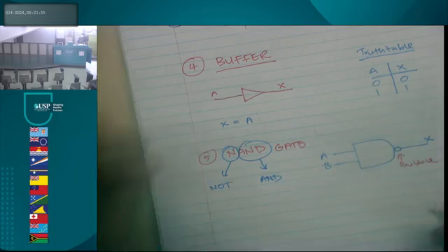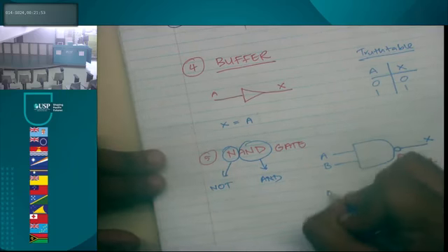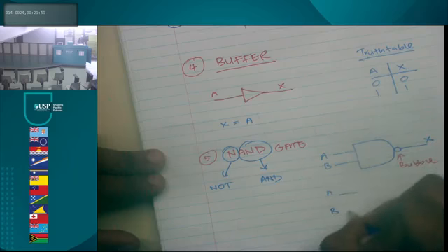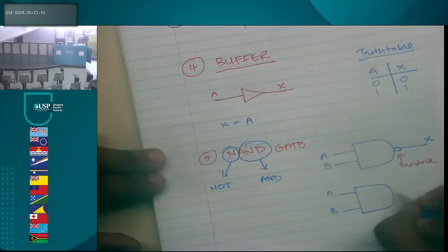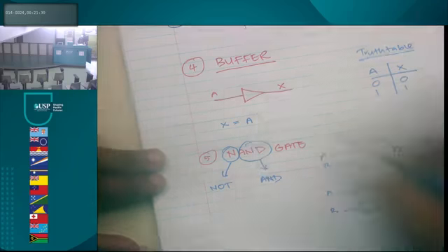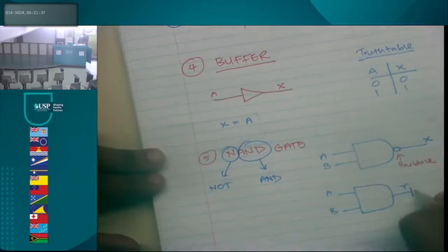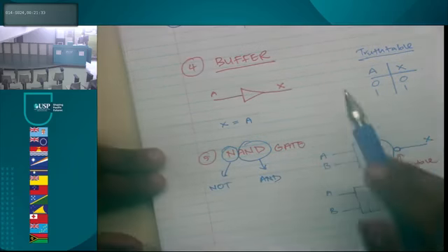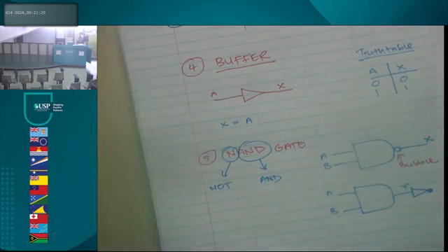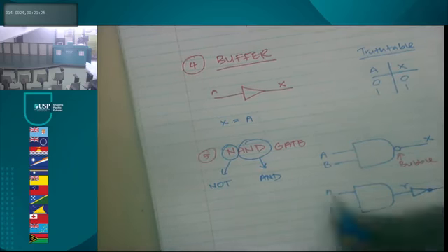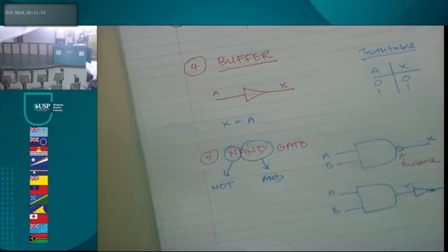Another way you can see this is if you have your inputs, right? Your AND gate, you'll have your output. Let's take a variable of y, and then your buffer. Buffer with a NOT, because buffer was just whatever your input is, your output. So we just use a bubble in the buffer, right? But don't worry, you'll never have to show this one. I'm just showing it to elaborate what a NAND gate is, right? So there.